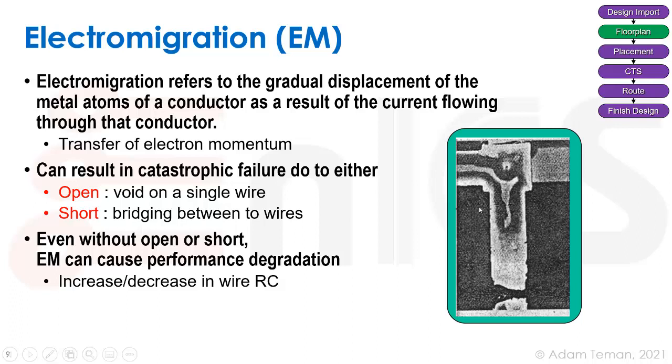But on the signal wires, in MOSFETs at least, in CMOS, we're driving a capacitor, so it doesn't keep on flowing through. It fills up the capacitor and stops flowing. There's not this huge current flowing on signals all the time, and that's why we used to only check electromigration on our power and ground rails. However, because we've done such heavy wire scaling and the wires really have high current density, now we also have to run signal EM, which is actually running electromigration checks on the signals themselves.